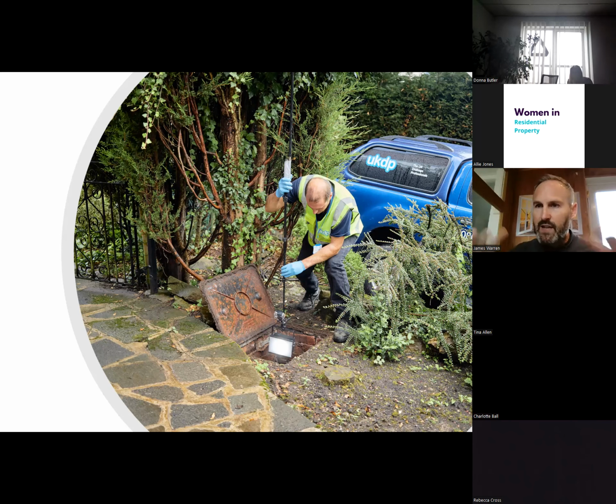Also, if we're there while the tank is being emptied and there's any water backwashing from the outlet pipe, that is another massive indicator that the soakaway has failed, that pipe work is holding water and it's waiting for the tank to be emptied for it to backwash into it. So it's all these things. You're listening and looking out all the time for structural breaches or water ingress or egress.